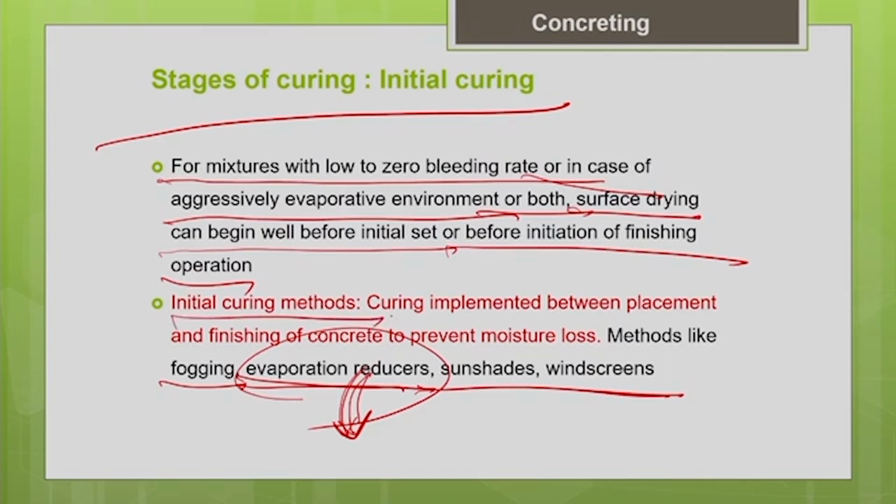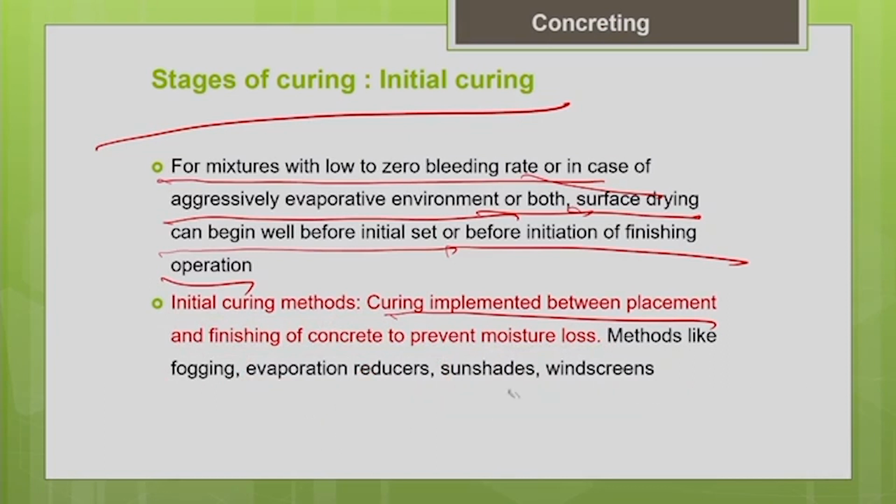Initial curing methods are implemented between placement and the finishing of the concrete to prevent the moisture loss. So, basically we do this curing between the placement of the concrete and the finishing of the concrete, to prevent the moisture loss. As I told you, even before the start of the finishing process you can do the initial curing.